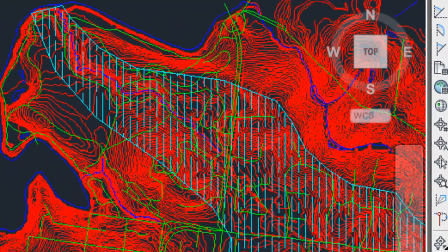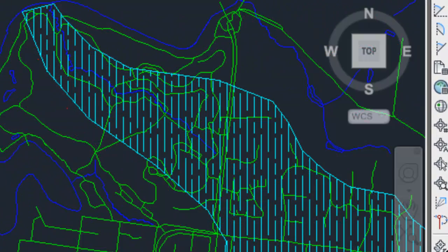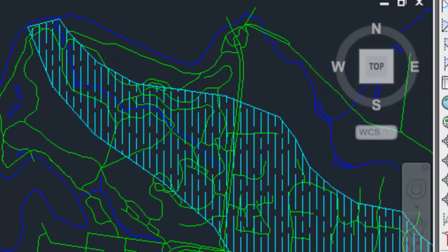There's our layer which we do need, and again, these are points inside the map, but we actually don't need this information. You can see little tiny dots down the bottom here. This is information that was put in to make up the contours. So we basically need to switch off all the layers that we don't need.